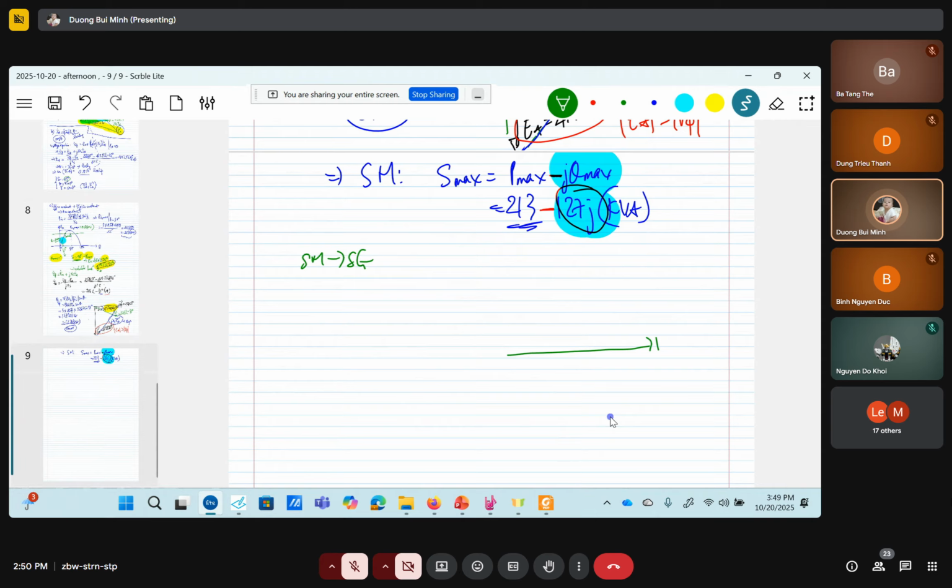So here we have V phase, and then here we can get the EA, and the phase angle here is 90 degrees. That means EA is 419.23 with a plus 90 degrees. So that means the synchronous motor becomes a synchronous generator.